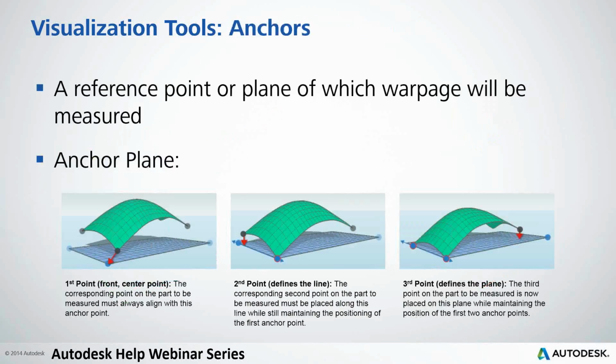Now, whenever you're, say, wanting to compare it to other studies or else wanting to compare it to your molded parts, how will you do that? That's where anchor planes come in. So this is another visualization tool. It's something within Synergy, so you can apply it after you run the deflection simulation. You don't have to rerun the results afterwards, but basically all you're doing is constraining the orientation of your part to a specific plane. So I always think of it as a fixture to orient that part in order to get the measurements that you're looking for.